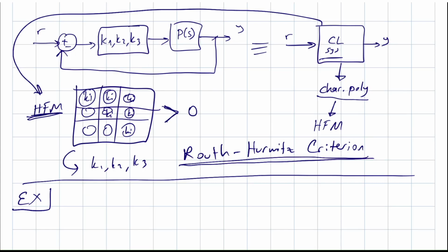By using this constraint, we are going to impose some constraints on our controller parameters K1, K2, K3. For example, it can be a PID or something. You are going to see that, for example, if each entry is a linear function of the ki's, what would you say about that constraint? You would say, yeah, this is an LMI constraint that we can handle.